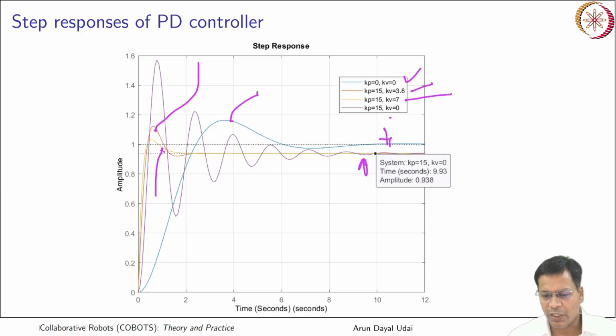This was the system with kv is equal to 0. Okay, so that is only stiffness with its own natural damping. So this is with only external stiffness, that added stiffness. So you saw it is oscillatory. I don't want to talk about that now. So three systems are here. The best one can be this one, which just overshot a bit. Steady state error is there.